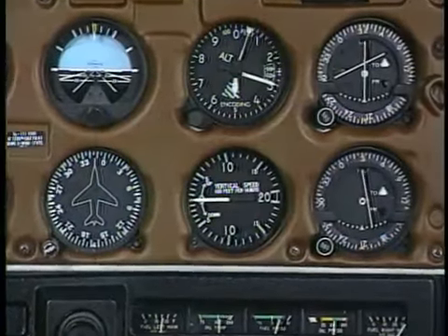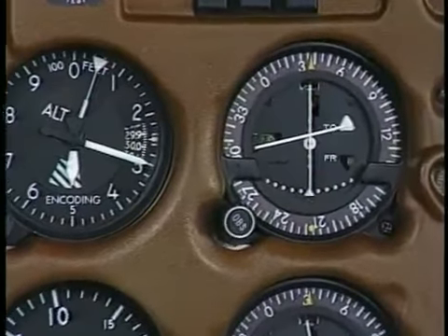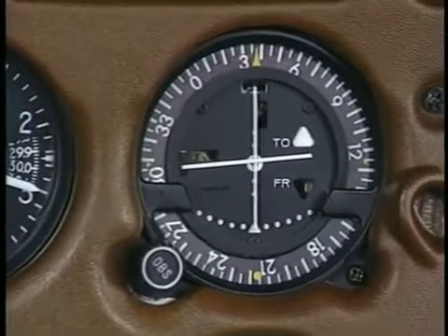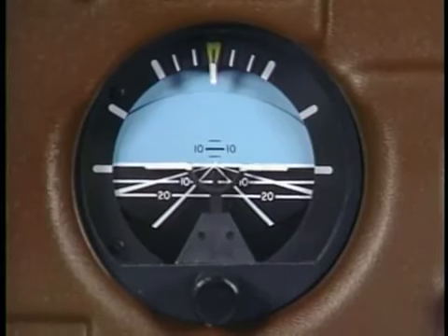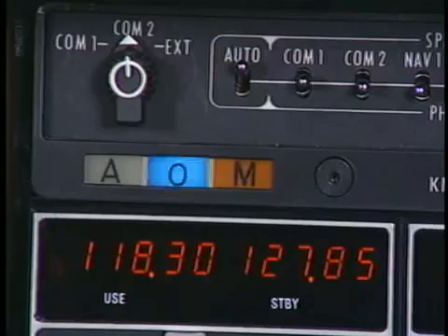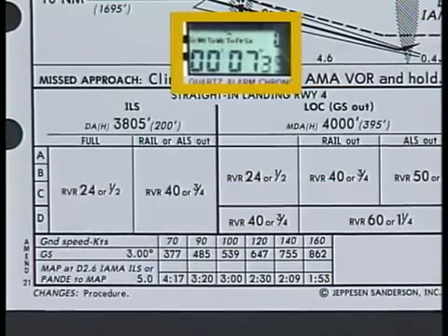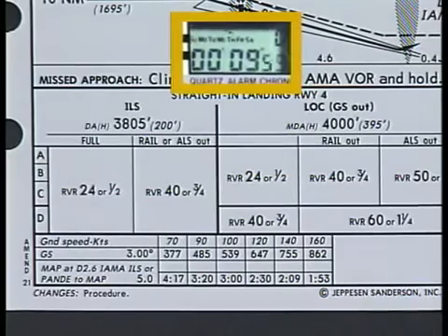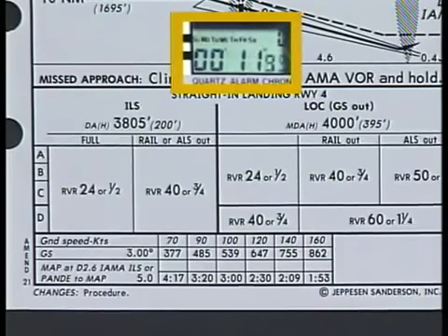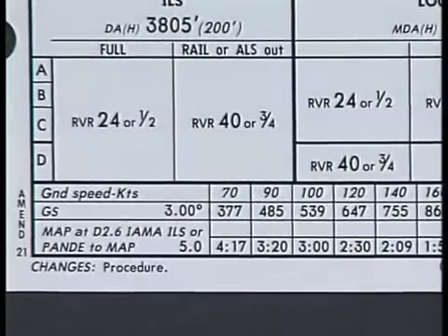As you near the glide slope intercept point, the horizontal needle begins to move down towards center. As the needle centers, you must make a small pitch, power, and trim adjustment to establish the proper descent rate and maintain the airspeed. It's a good practice to note the time as you pass the outer marker. If the glide slope stops working, you can still continue with a non-precision localizer approach, since you'll have the timing needed to identify the missed approach point.